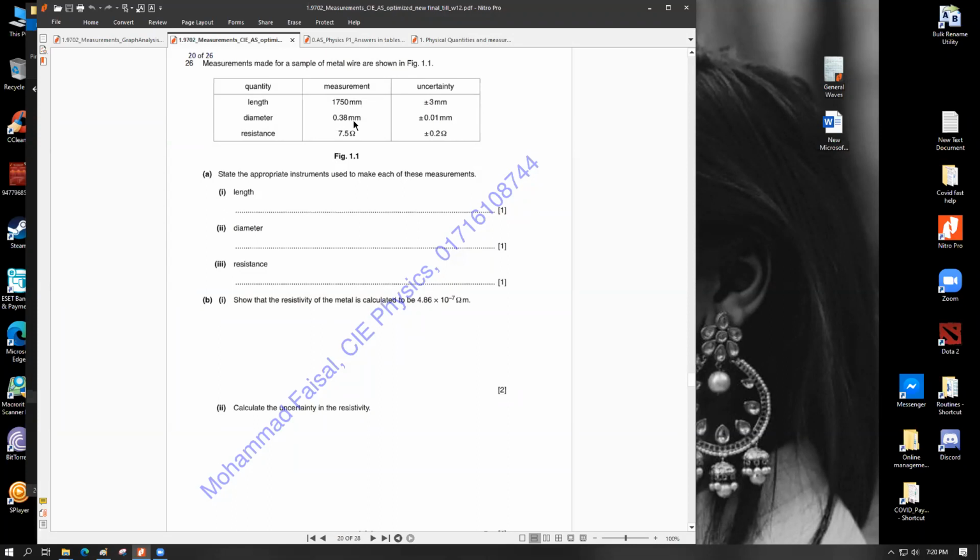Kids, try to grasp this idea. You are measuring the length of a certain object, and let's say for that length measurement, once you got 3.6 centimeters, once 3.7 centimeters, and once 3.6 centimeters. When you mathematically average the three values, you're going to get a fraction of 1 millimeter, which is perfectly good because a mathematical average is a calculated number, whereas the raw values were 3.6, 3.6 and 3.7. The raw values of a measurement device can never be something other than a full multiple of the uncertainty of that device, whereas the calculated value, namely the average, can be anything.